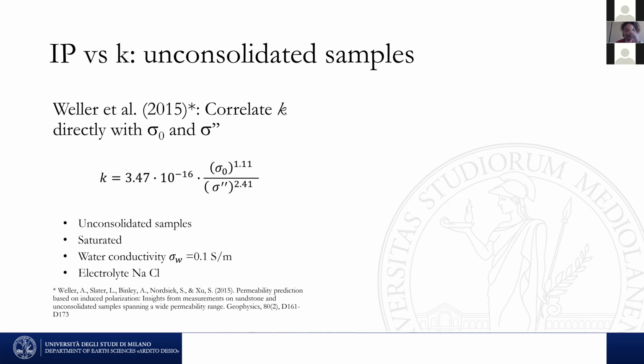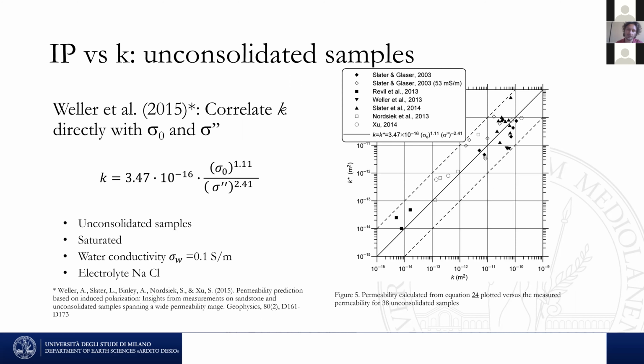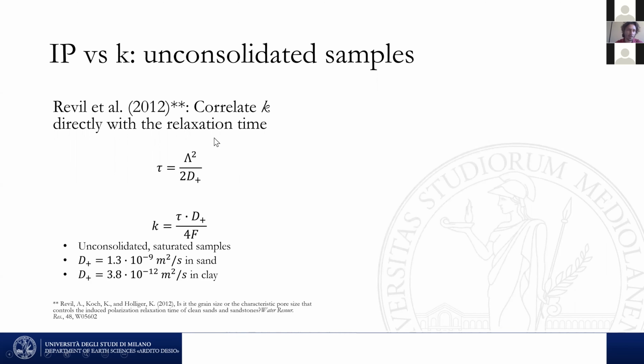and with a specific electrolyte. But the good thing is that this formula really depends weakly on the water conductivity. So this can be used in a much wider set of situations. And this is the kind of link that was found in the lab between K measured through hydraulic methods and K estimated by IP. The second approach from Revil, for instance, and other authors, links the relaxation time of